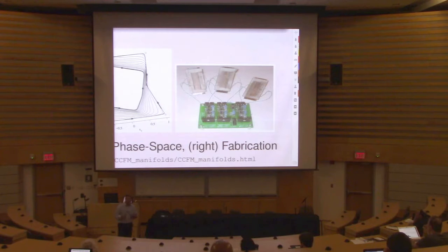Eventually, we measured and calculated that about 1 foot of cable translates into 1 nanosecond of delay in the coupling circuitry. And this is the actual coupling circuitry where we apply just a small amount of excitation into the system to get it started. So we were able to show that we could increase sensitivity, and the best we got was somewhere around 100 picoteslas. So we went from 250 microteslas to about 100 picoteslas.